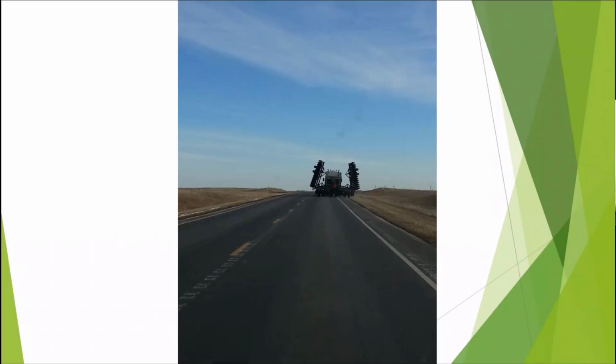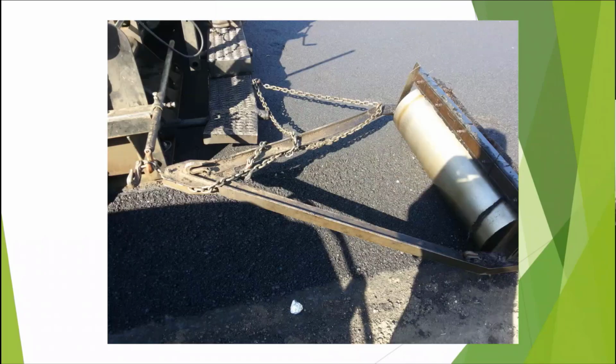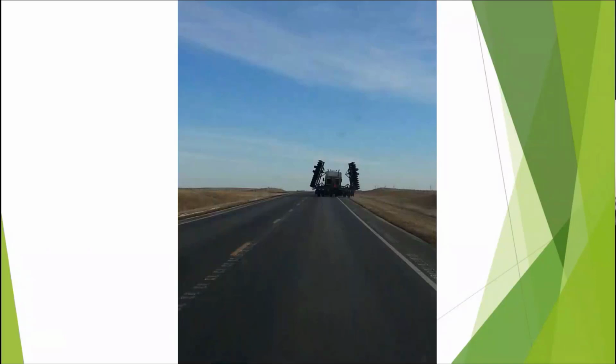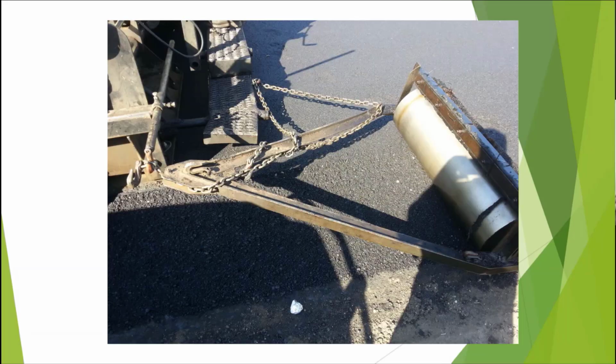Last thing I was going to close on is the edges. Why do we worry about the edges? That's non-pay tonnage, right? Outside that fog line. Well, there's why. More and more in our part of the world, heavy loads, oversized loads, where do they run? On the pavement edge, on the shoulder, where we don't even necessarily worry about compaction and ordinary compaction, right? So you need to roll that edge, particularly the inslope, the slough, because to get it closed off,